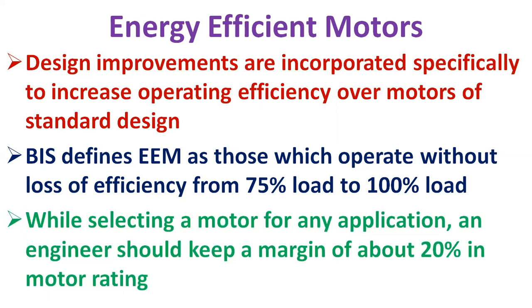In India, Bureau of Indian Standards defines EEM as those which operate without loss of efficiency from 75% load to 100% load. Moreover, the mounting and overall dimensions are designed as per IS 1231, making it easier to replace the standard performance motors with energy efficient motors.